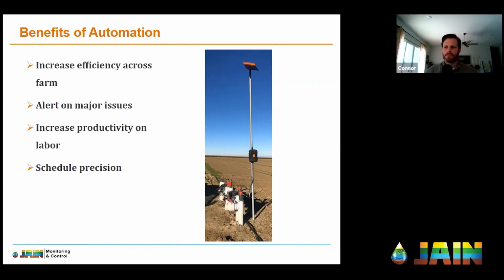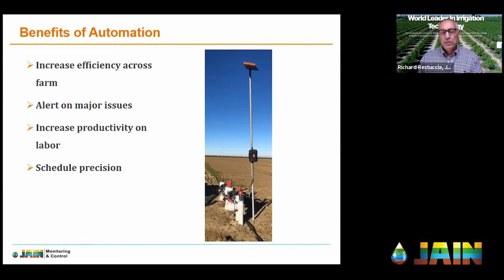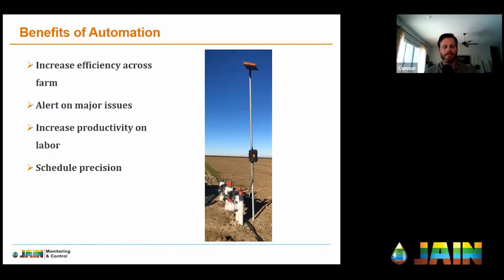That's great. Now, Connor, looking at this photo, can you tell, is that set up as a gateway or a node? Yeah, I can tell that it's set up actually as a cell because it doesn't have a very large antenna on it. There's nothing on there that you would say, that's an antenna. To the untrained eye, you can't really tell, but on the top of that enclosure there's a very tiny black little nub, and that's a cell antenna. So that's how you can tell the difference between the communication types of a C3. If there's a large antenna on the top of the mast, that's a radio. And if the antenna is not very noticeable, or if it's very small like that, it's a cell application.